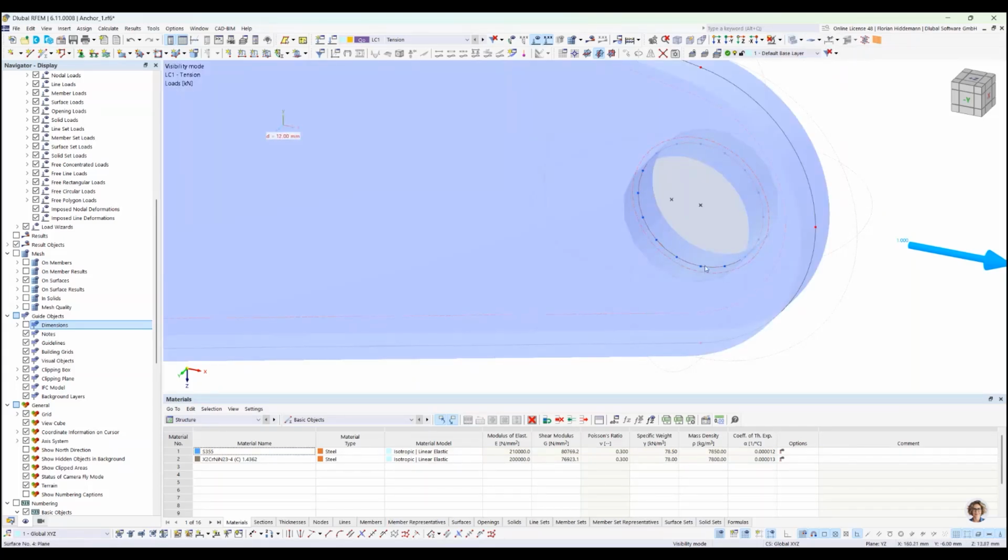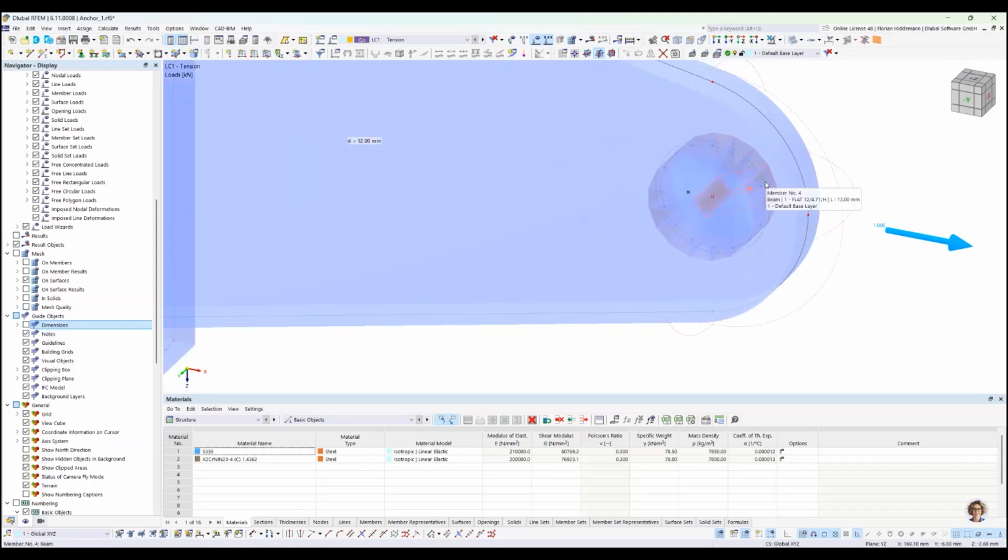So if we make them invisible and show the transparent model, then I choose a surface here where you can calculate with the diameter and pi the surface of the cylindrical area, and then model some beam elements which would have the same area. We made some good, this is our recommendation for how to model this kind of screw connection, to have some effects regarding displacement of the hole itself and let the force find its way into the connecting plate.